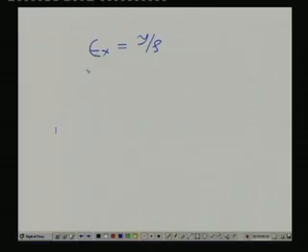So, what is the stress? Sigma equals E into epsilon x, which comes out to be E y by rho. So we can see the stress is varying, for a given bending moment, with E and rho constant. So, the stress varies with the distance y from the neutral axis.